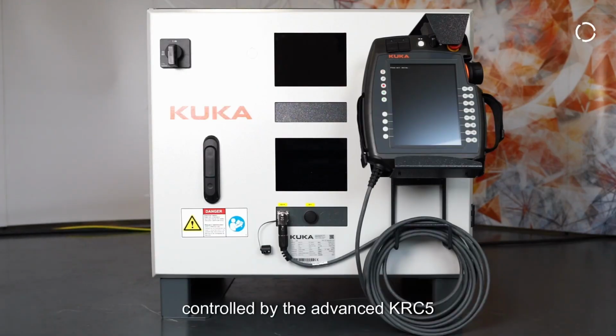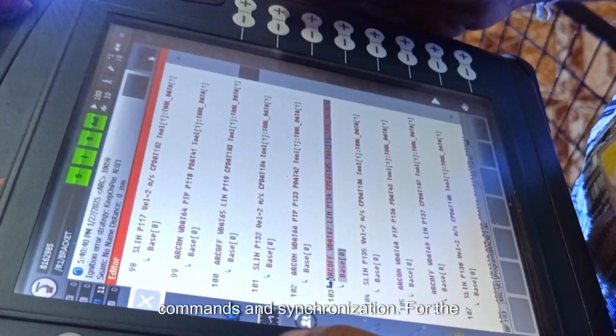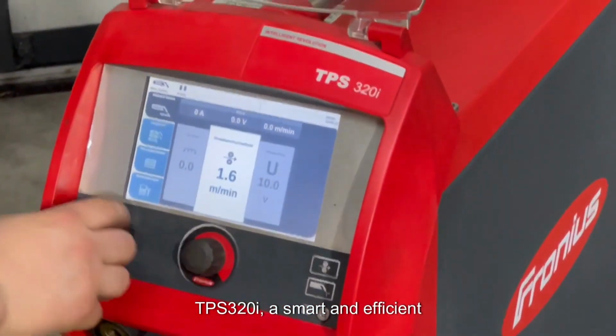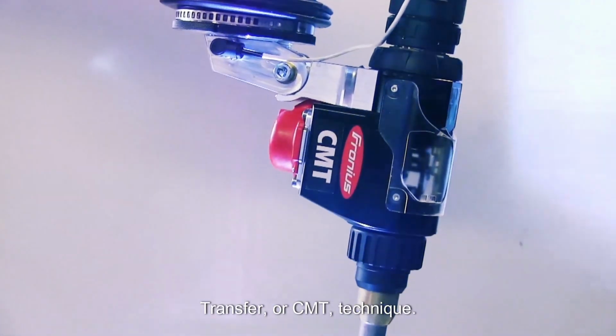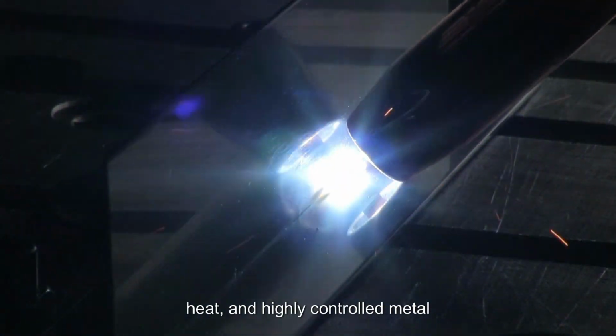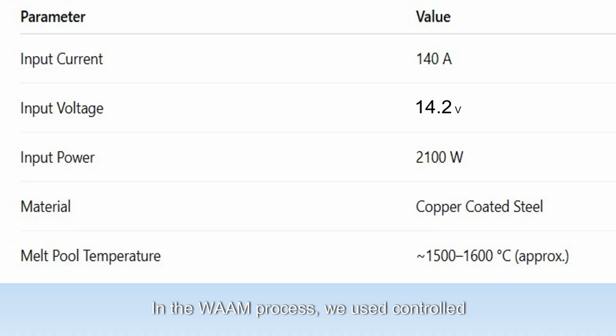This robot is controlled by the advanced KRC5 controller, which handles all motion commands and synchronization. For the welding process, we used the Fronius TPS320i, a smart and efficient welding power source, perfect for our application. We used the cold metal transfer, or CMT, technique. This method allows for low spatter, low heat, and highly controlled metal deposition, which is ideal for 3D printing metal parts. In the WAM process, we used controlled welding parameters that are 140 amps current, 14.2 volts, and a 3.7 meters per minute wire feed, for smooth deposition and minimal spatter.